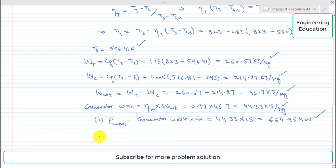Second, we have to find the cycle efficiency. For that, we will need the heat supplied. So heat supplied in this case is equal to Cp into (T3 minus T2). So when we put the values, Cp will be 1.15, T3 is 823, and T2 is how much?